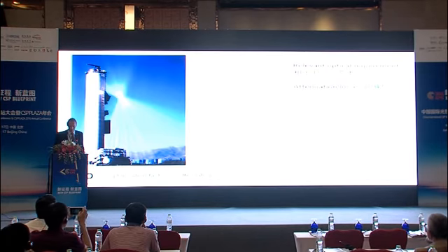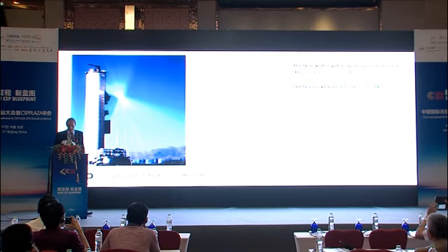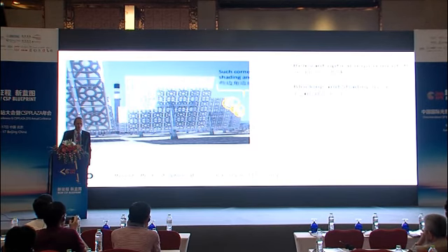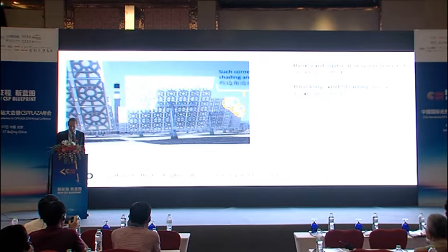Another important factor is the attenuation losses. That's related to the air quality and to the visibility. To optimize this, you would place all the heliostats as close as possible to the tower and decrease the distance of the sun rays being reflected. But at the same time, you have the problems of shading and blocking, which means that one heliostat blocks the other or they shade each other. That's a picture you can see here.